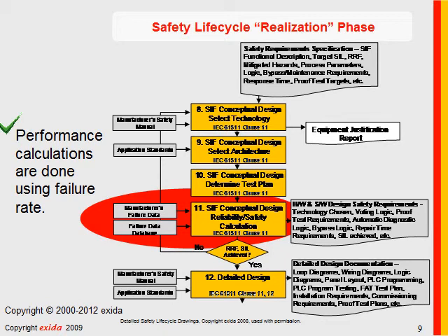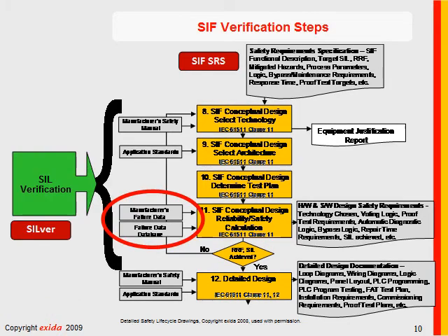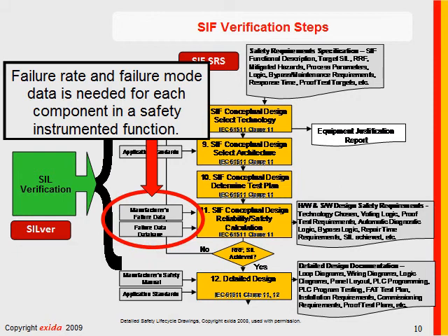There are no prescriptive rules about any particular design that must be used for any particular SIL level. Engineers are free to create their own designs and to optimize cost. But in order to do these calculations, failure rate data must be available. Failure rate and failure mode data must be available for every part in the safety instrumented function.